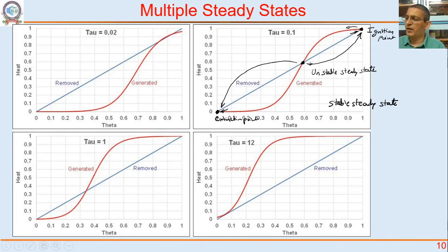Now you see, as per your undergraduate course where you had thought of only isothermal reactions, you had thought CSTRs were so easy, well mixed reactor was so easy, concentration is same everywhere. Now all these complications come in because now reactions are exothermic. There is a dynamic balance between the heat generation and heat removal that can give rise to multiple steady states. So deciding residence time in the reactor, deciding where I should operate my reactor, also depends on whether I have a stable steady state or an unstable steady state.